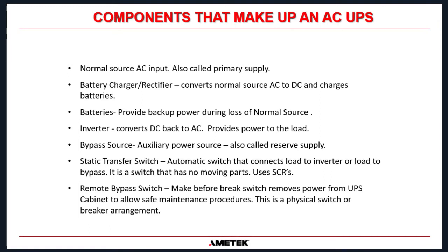Then we have a static transfer switch. Don't get this mixed up with an automatic transfer switch like you have on generators. This is an automatic switch that connects the load to inverter or the load to bypass. And it is a switch that has no moving parts in it. There's absolutely no moving parts in a static switch, hence the name static switch. It uses SCRs, which are silicon controlled rectifiers, to do the switching. So there's no arcing, and the switch switches instantaneously. Obviously, with a mechanical switch, there is a time delay from when the contacts open to when the contacts close and vice versa.